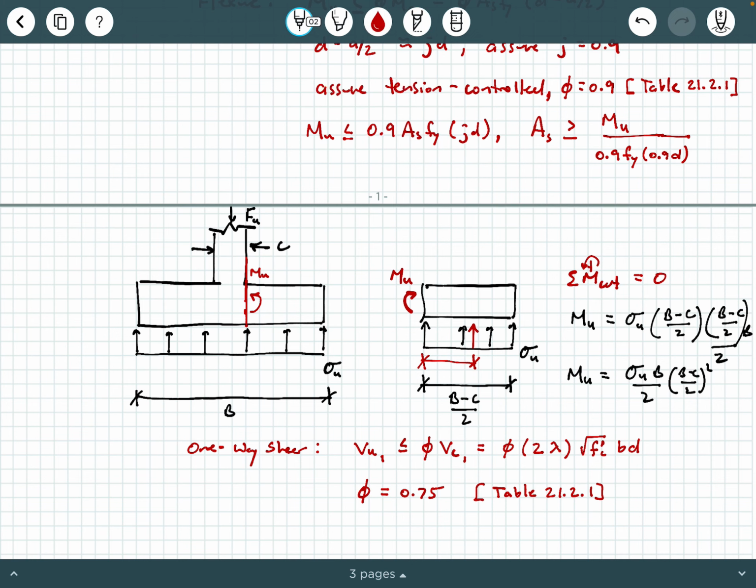Now, what if you have a steel column, or you have a masonry column or a masonry wall? Where is that critical section? Well, I'm going to put a note here. I'm going to say ACI 318-14 Table 13.2.7.1, because that has other critical sections where MU is located. If you have a different kind of column or a different kind of wall, let's say you have a column on a steel base plate, or let's say you have a masonry column or wall.